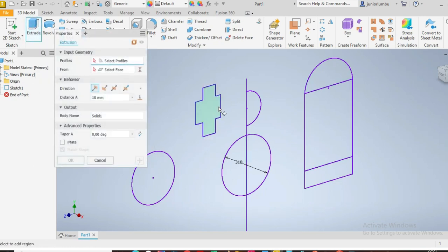With extrude, you are adding up the material. So if I click here, now they're asking me, do you want to add 10 millimeter on this figure here? Then I'll say yes or no. So how? I'll either confirm by saying okay, or I'll just say no. I'm going to add 25 millimeter. I type on my keyboard 25 millimeter.